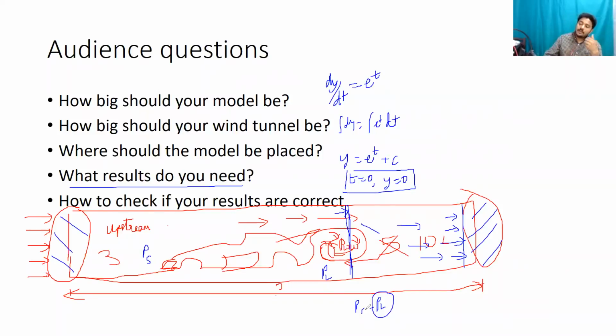So when you are solving the Navier-Stokes equations in CFD, it will calculate the pressure and velocity. Now your velocity gradient is going to determine your shear stress, and pressure is just computed from your continuity equation. Your pressure should be calculated in such a way that the velocity that you get should satisfy the continuity equation. This is called pressure velocity coupling. This is a term that you might have seen in say ANSYS Fluent or any other software, right? So you need to be getting those results correctly.